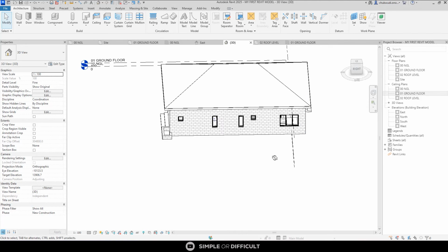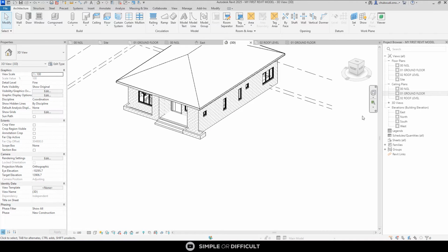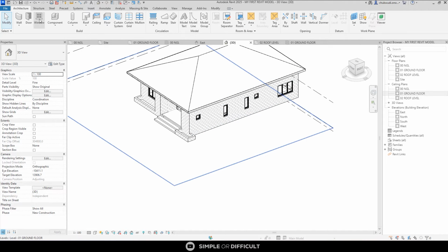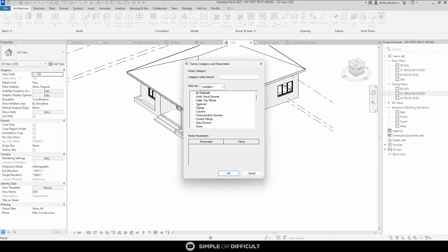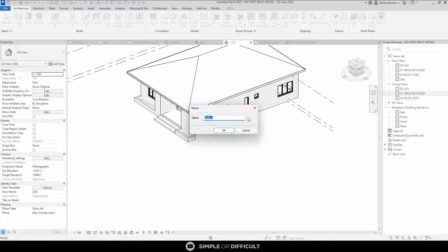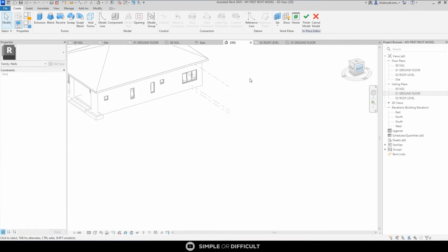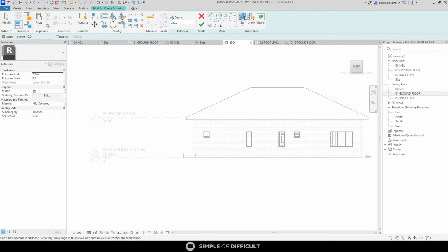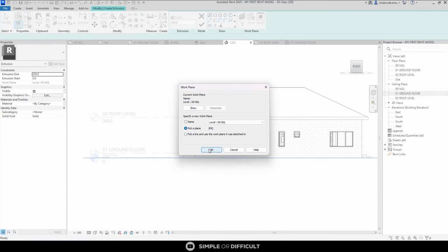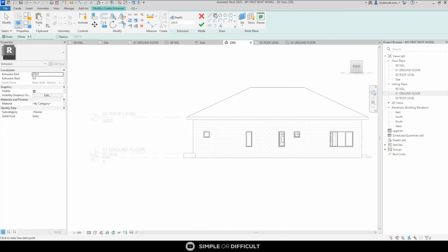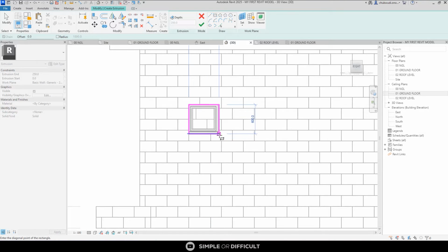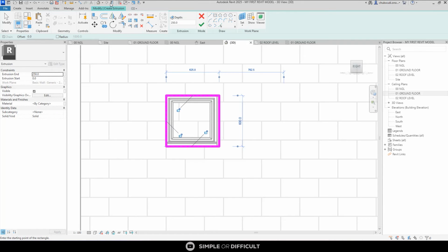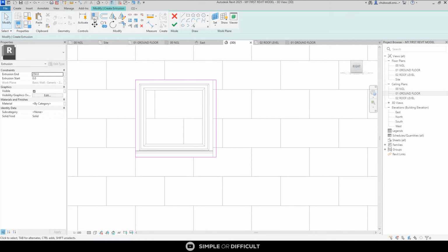Now it's time for us to do the facade design. Okay, very simple facade design I want to do. I'll do model in place and then set it to walls. Okay, and then I'll do extrusion on these walls. I want to set the work plane where I want it to be. And I'm going to frame all these windows, so I know what I'm dealing with. Ten lines.